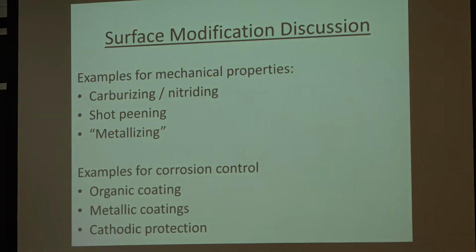Okay, so that leads well into surface modification that I wanted to discuss with you from just a general perspective. So let's say we've made some parts and now we want to use them. We can make the surface harder. And some of the advantages, again, is wear resistance and fatigue initiation, because you raise the yield strength on the surface.